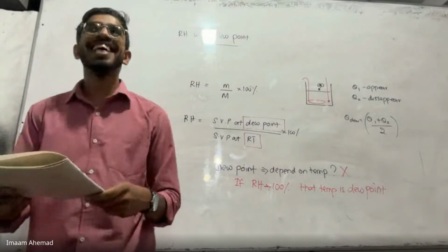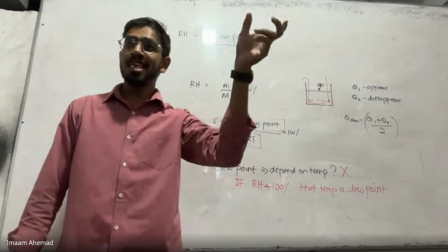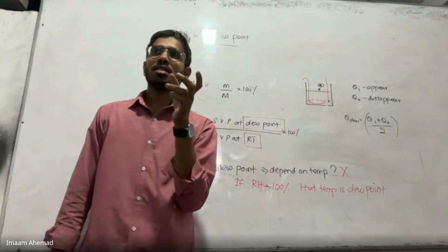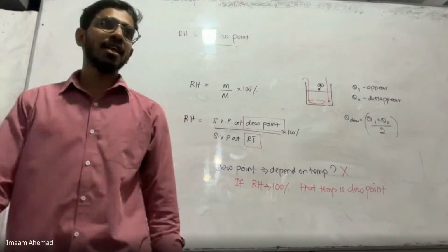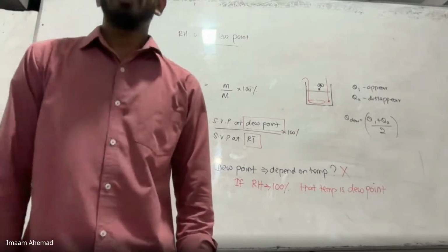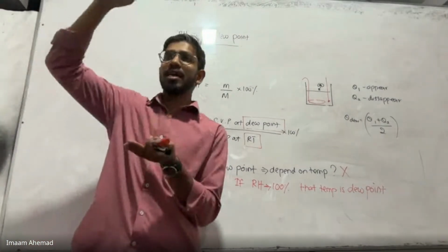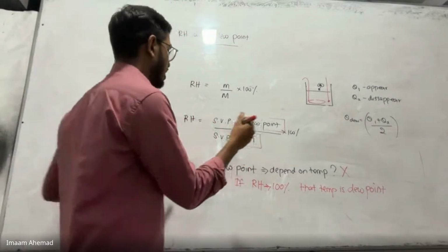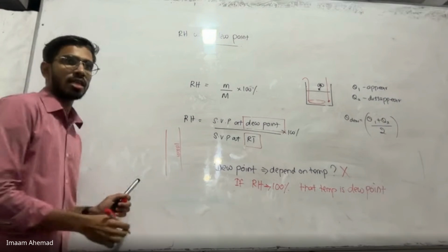Yes. So which one is better? Minus 10 to 50. What's the reason? Using minus 10 to 50 is better than using minus 10 to 100. Why is that? Now, just think, if the thermometer is measuring a higher range, the calibrations on the thermometer will be very, very close to each other.